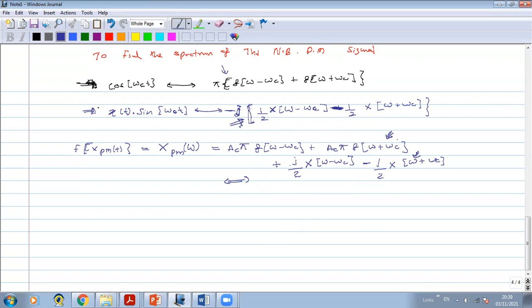So when we look at the spectrum using a spectrum analyzer, this part we can't see, and we can see only this one and this one. In the laboratory, you can verify that. In a spectrum analyzer, we can't see the minus frequency, only this frequency. If I draw the complete spectrum, it will look like this.